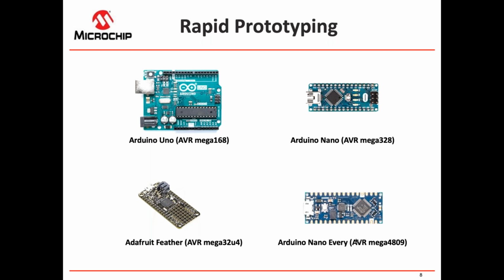No more than 10 days ago, Arduino did another launch at the San Mateo Maker Faire. And you might have seen that they launched yet another round of Arduino Nanos. And here's just one of them. I think there were 6 models in total. This is the Every. Again, it's a Mega there, an AVR. And this is the latest and greatest Mega, the megaAVR 0-series family. So they put there 48 kilobytes, so they triple flash memory and triple RAM versus the original Mega. But they included also many of these Nanos, including radios and including IoT solutions.